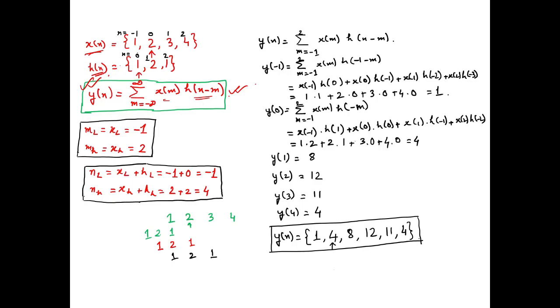in the previous section, we have inverted the time. So when we have inverted the time, we have changed the time axis. This time axis is being changed for this reason, and that is being incorporated over here: x[m] multiplied by h[n minus m]. Now, in both the cases, if you see, both are time limited signals, they are present within a certain time. So what should be the values of these limits?